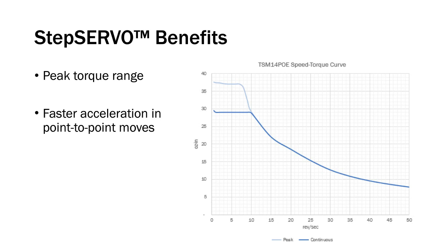Is the PD specification per port? When you're looking at an Ethernet switch, the question is, when a switch rates how much power is available, what does that mean exactly? What I've seen most common amongst switch manufacturers is they give what's called a power budget. Let's say you have a 4-port switch, and each port is rated to provide up to 30 watts.